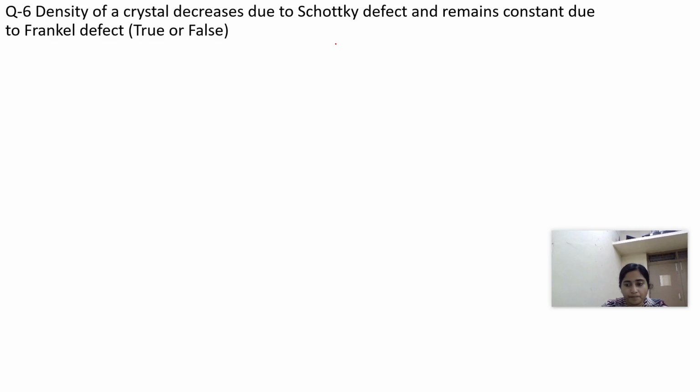So mainly temperature will cause the Frenkel defect, and you can calculate from that. If we are heating a material, there is a possibility that it will form a vacancy or it can form a Frenkel defect. So how can we differentiate whether a Frenkel defect or a vacancy will be formed?